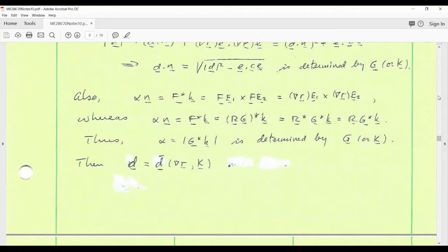So that's satisfying to know. However, the price we pay for going from 3 dimensions down to 2 dimensions is an additional complication in terms of additional structure in the theory. So not only do we have a deformation, in this case the midplane deformation, but we have these so-called directors, D and G and H, that we talked about, which give you information about the three-dimensional deformation in the vicinity of the midplane.